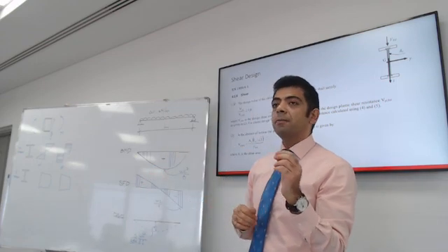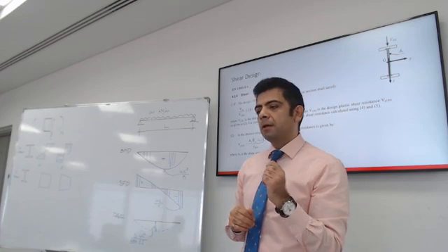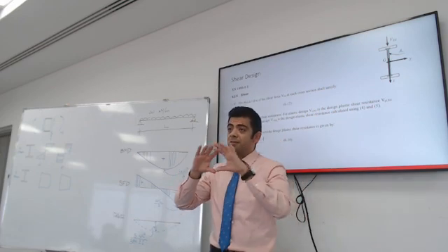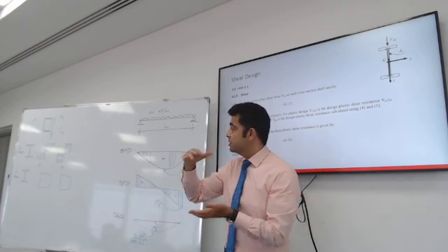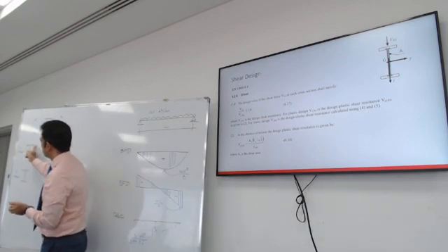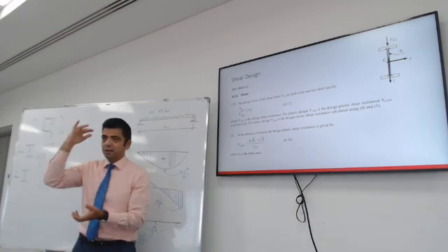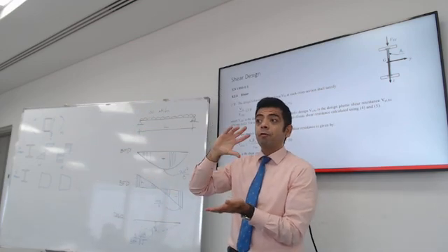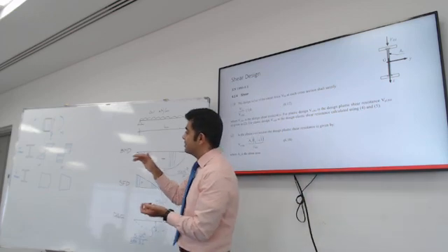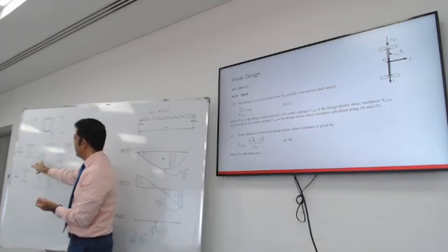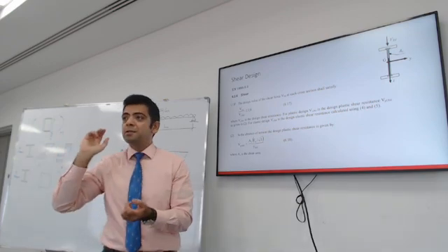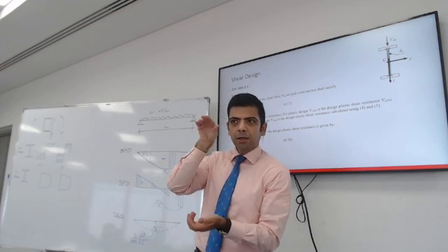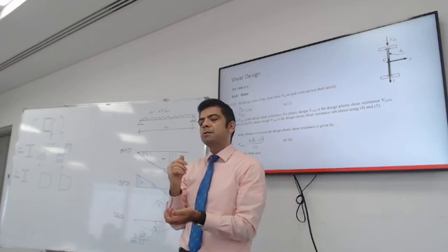I want to point out something very interesting to know in terms of design. For steel beams, the top and bottom flanges, these are the horizontal parts in an IPE section, are critical for bending, because bending stress has maximum stresses at the top and at the bottom. So we care about lateral torsional buckling and the yield strength of the section and so on.